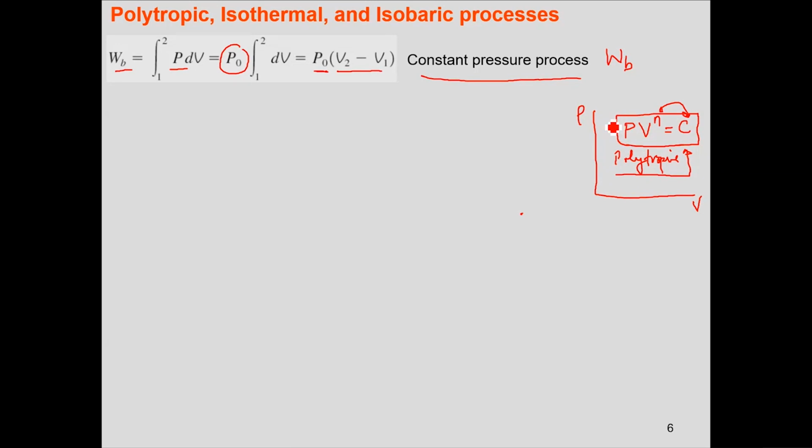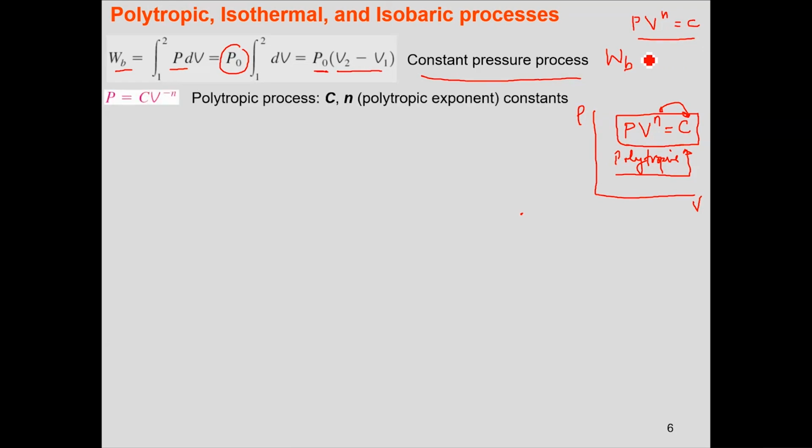And when I say a polytropic process, I mean a process which is following this generic equation, PV to the power n equals constant. The n value would determine the shape of the path, but if a substance or a fluid or a gas is following a polytropic process, you will have essentially this relationship. In case you have this relationship, what would be the boundary work? Let's say this is a polytropic process. PV to the power n equals constant. It is the same thing.